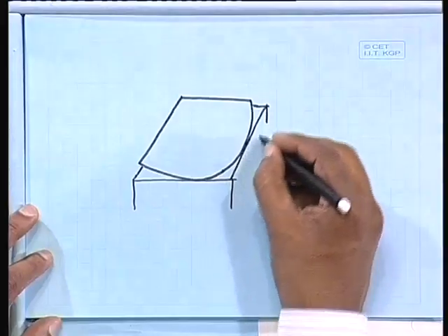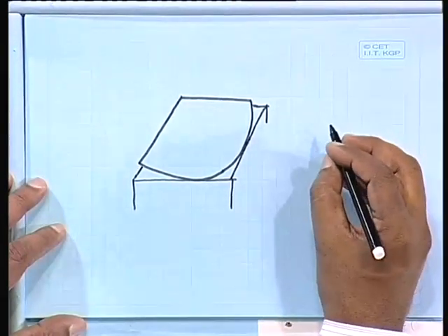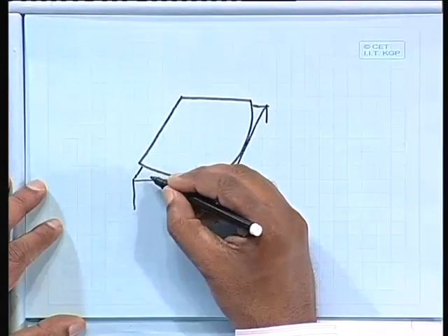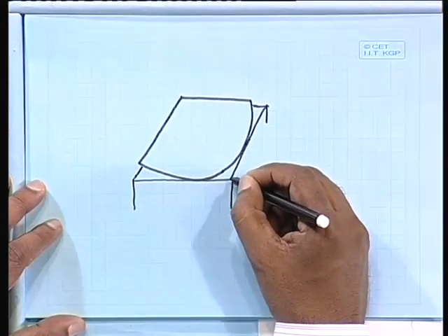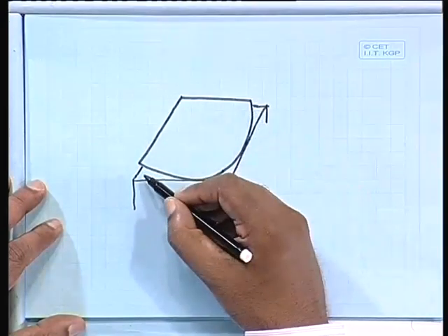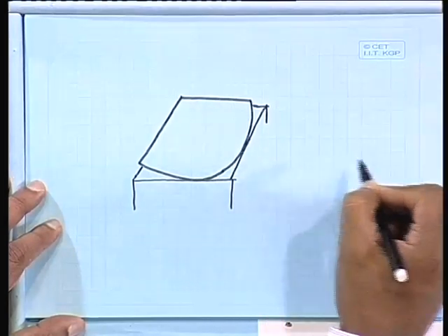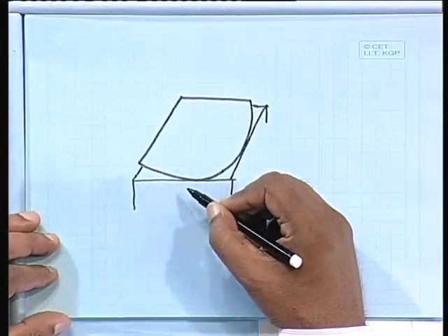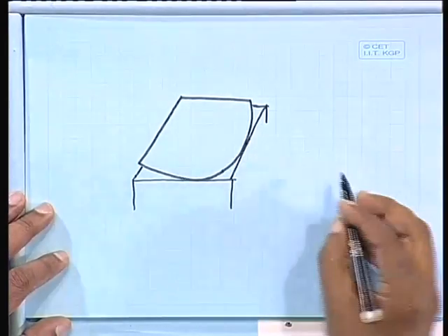So, it is true. Here what I am trying to show is that there is one possible case that corners are restrained or corners are not restrained. If you have to restrain your corner, that means you have to provide reinforcement in each corner. But that is true only where we have to provide the reinforcement. We have to provide the reinforcement only in the corner that is discontinuous. The corner which is the support which is continuous, there you need not specify. We have to specify that reinforcement only where the corner is isolated, one portion this way or the other way, but not like this.